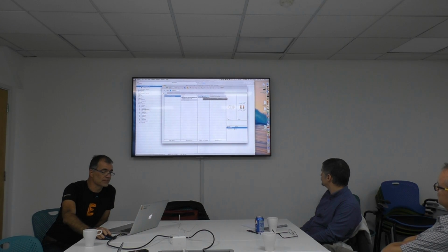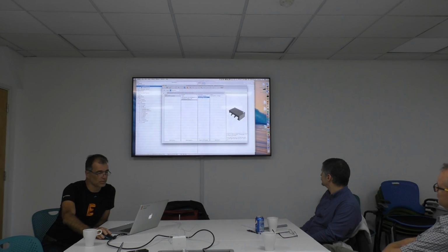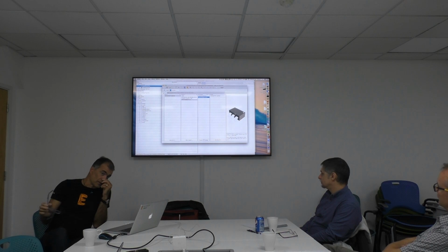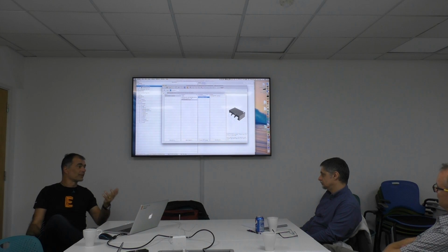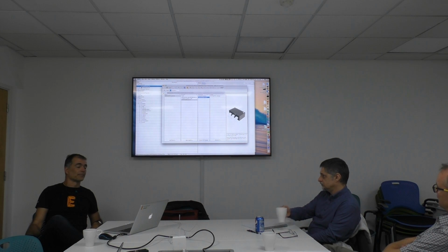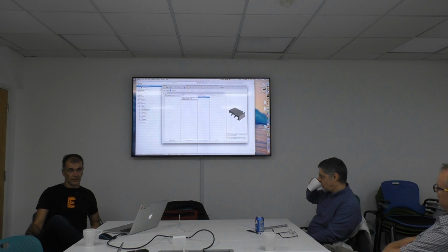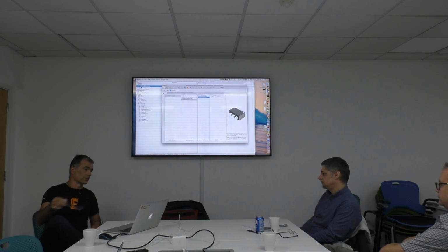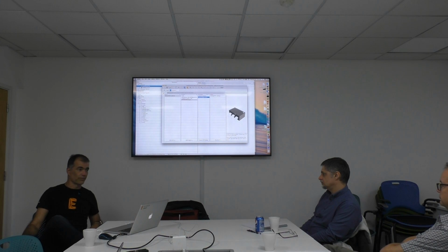And the next step, of course, is yes, I would like to have a 3D package. This one, this one. How do I get 3D packages? You could design it in Fusion, for example. This is an option. But in most cases, the manufacturers have 3D models. If you go, for example, for connectors, most manufacturers offer the step models in most cases for free. And there are different sources in the internet where you can download 3D models for all kind of electronic components.